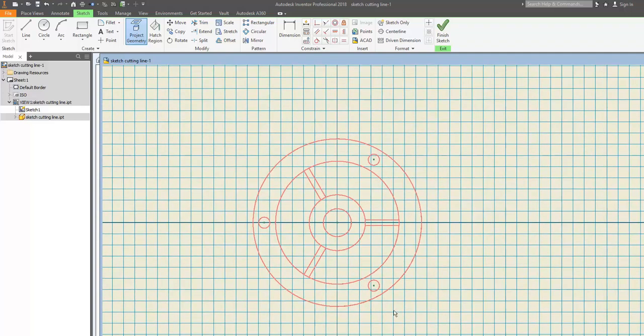Okay, then I'm going to cut the body starting from here, locating the edge of the cutting plane as coinciding with the radial axis of the hole, and then move from here to there, and then cut the rib, and then reach here, the center of the body, and then change the direction and cut this rib, and then while following the edge of the cutting plane, which is circular in shape, reach this cross section and cut this drill till the outside.